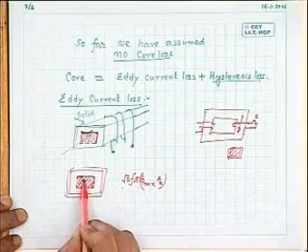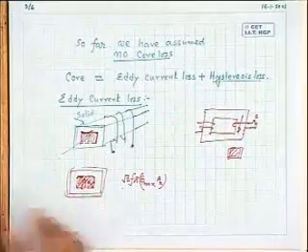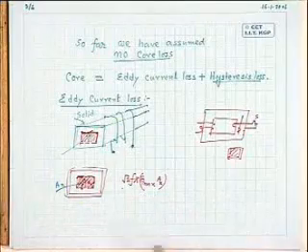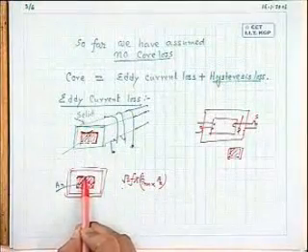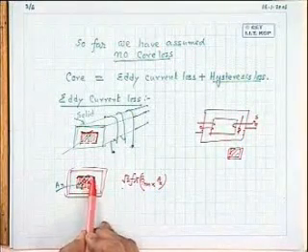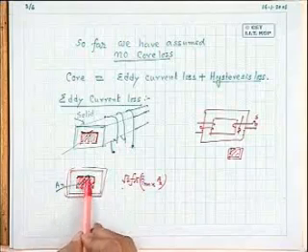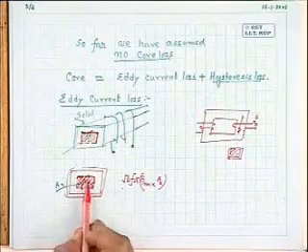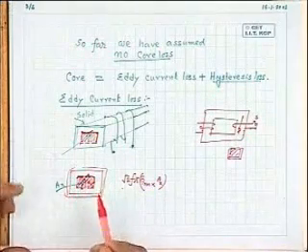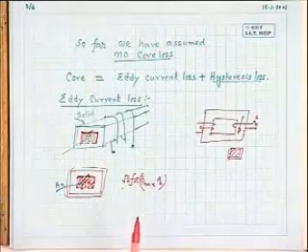Say some area, whatever it is, you call it AX. This area is AX, into N is 1. This much induced voltage is there. But this induced voltage in this coil, the switch is already closed. So why will this induced voltage not drive some current here? Suppose you imagine this imaginary path is somewhat open, I have closed it, then some current will circulate.